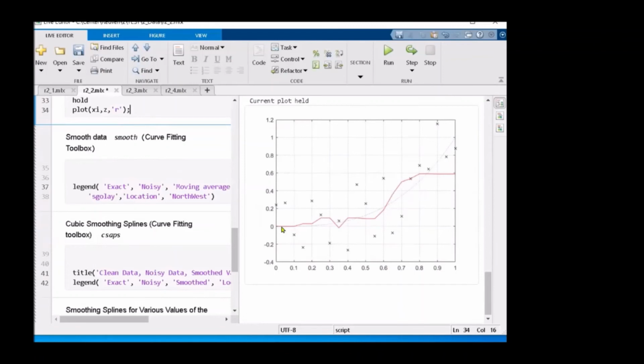What we have here, you can see, is the result of the median filter, just a moving average filter. How it works: it takes at each step 10, for example, in my example, 10 neighbor values, and just makes from them an average value. And this is our first value. Then it goes for the next 10, and each time it estimates the average and produces the result.